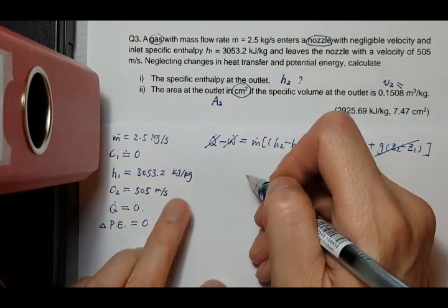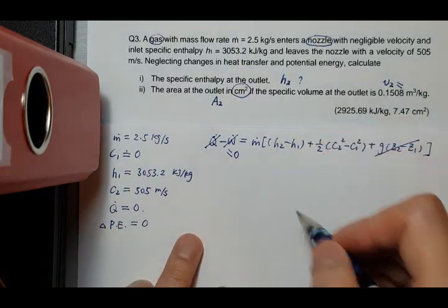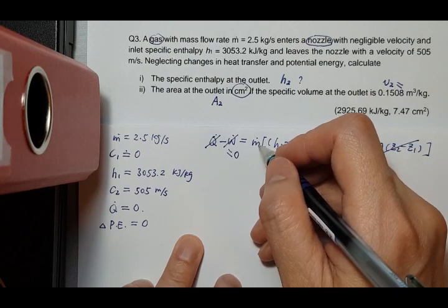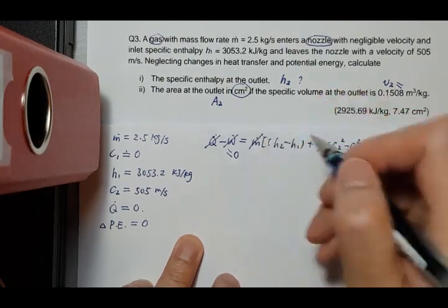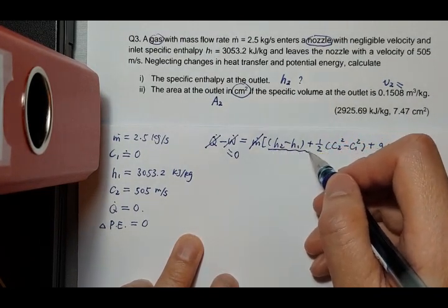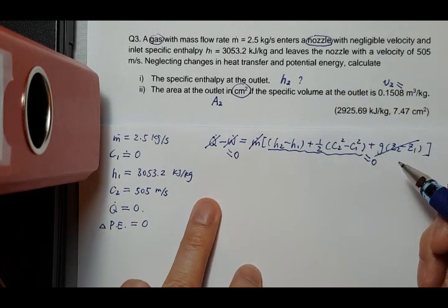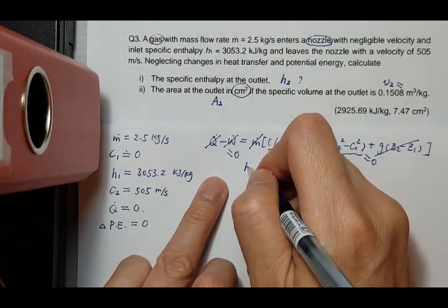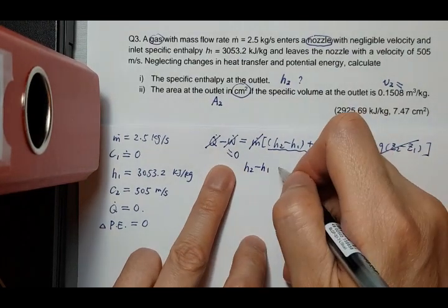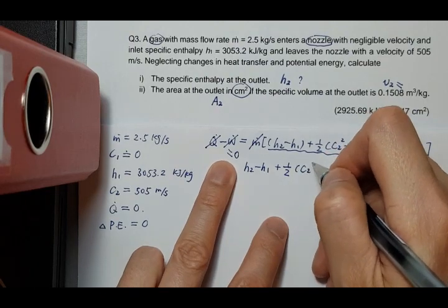So on the left hand side, we got both terms as 0. Okay, so that's why we can actually divide by m dot on both sides as well. So 0 divided by m dot will still be 0, and m dot here can be deleted as well. So now we just got here, this has to be 0. Okay, so this is how we simplify the first law of thermodynamics according to different devices based on different assumptions.